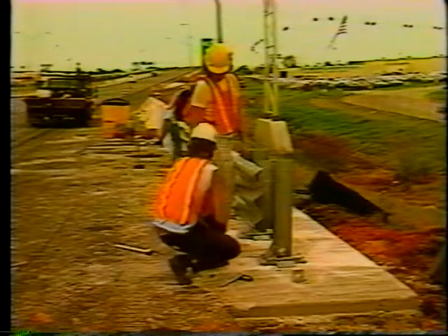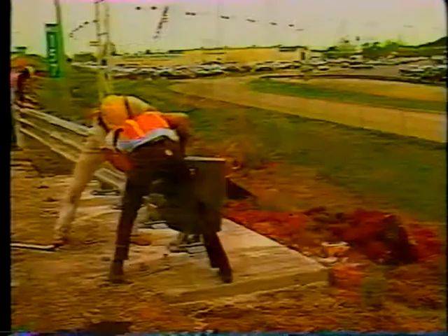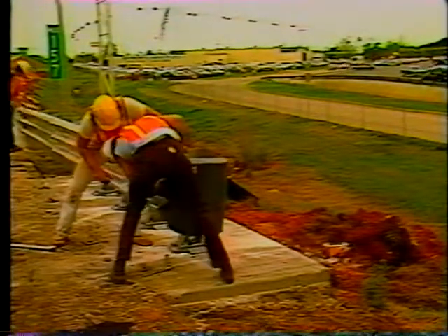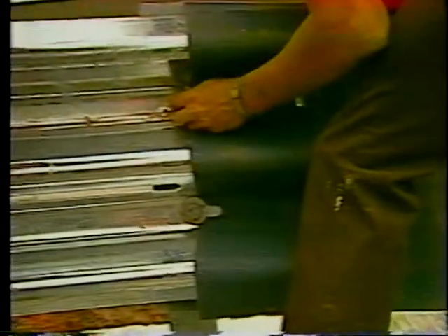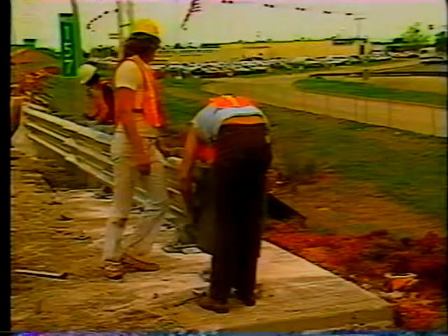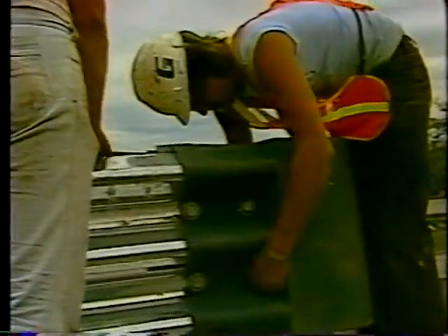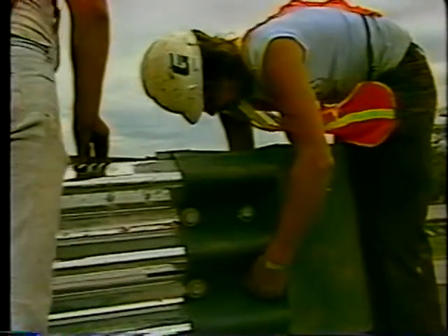At post 1, the 3/4 inch bolt assemblies must be left loose. The plastic bull nose is positioned over the panel but under the flat washer and bolt head before tightening the bolt assemblies. 2 bolts are also placed through the 2 remaining holes in the bull nose and through the 2 fender panel holes labeled G.